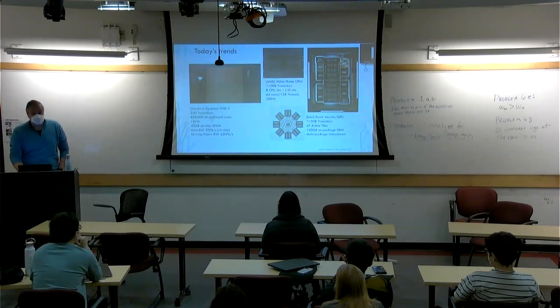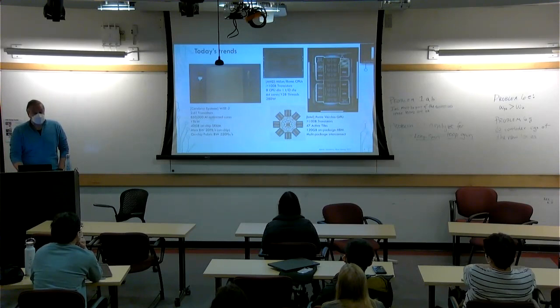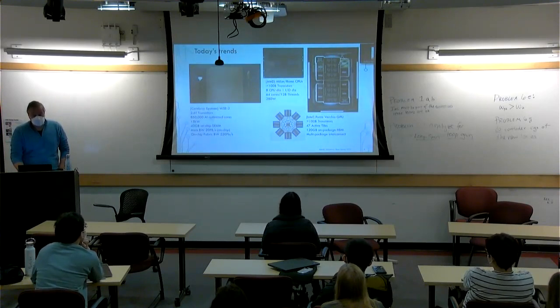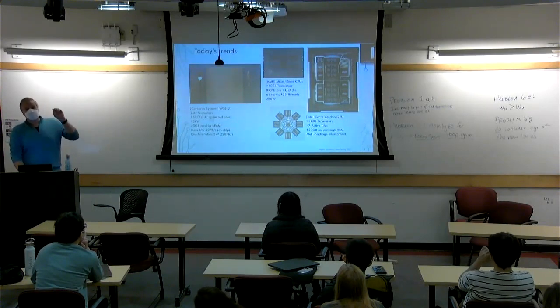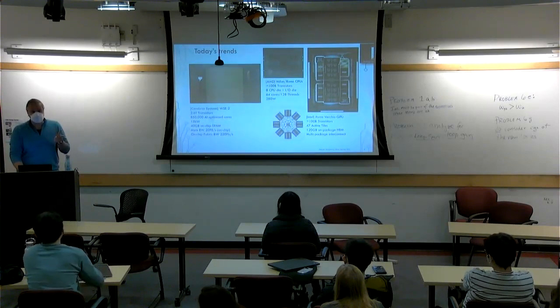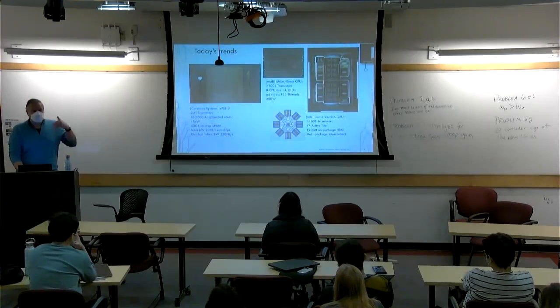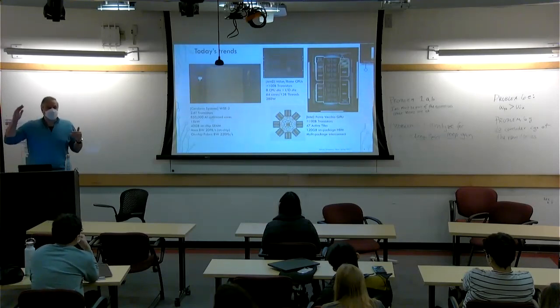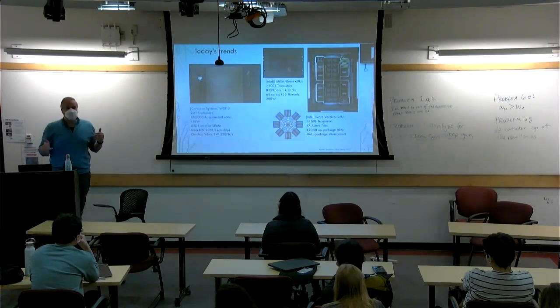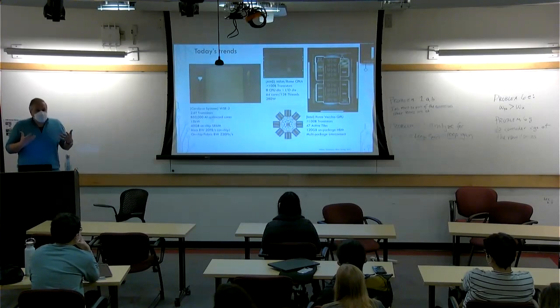You have triplets. This is kind of the AMD approach. You design this little core chip here, which is like 8 cores. So that's considered easy to design and easy to fabricate because it's a relatively small chip. Then you just select the ones that work and you package them on an inexpensive package. And then as the process continues, you keep scaling these little chips from 16 to 7 to 5 to 3 nanometers. And you kind of eat up the yields because the chip is relatively small.